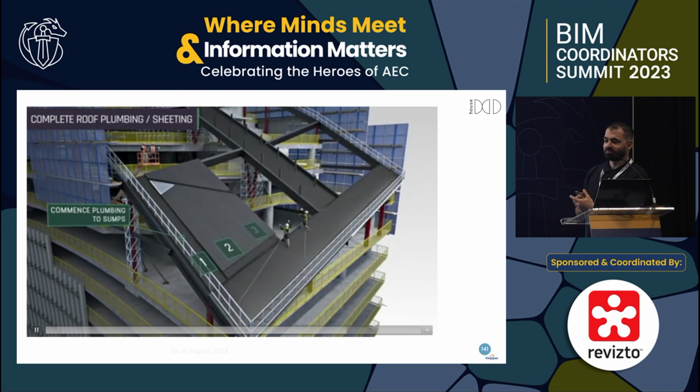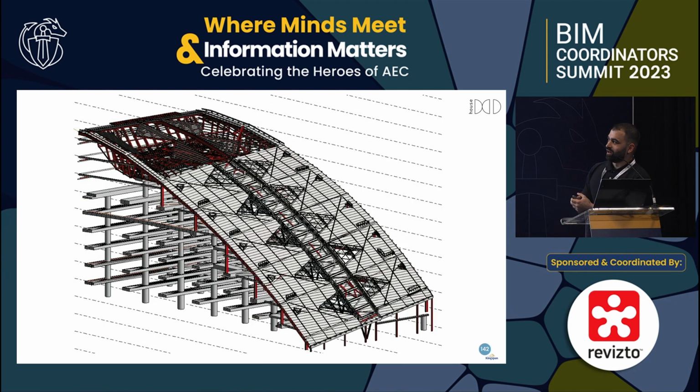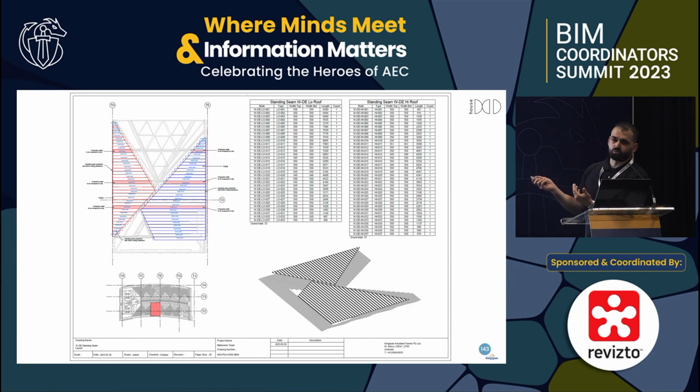Easy at the end. This is the building BIM model that we came up with at the end to mainstream that. Just to give you a perspective on how these were developed internally within the BIM environment, this is a shop drawing sheet that shows the components of the final layer of the sheet, which is the standing seam sheet itself. So the manufacturing facility needs these cut lists to produce it and then install it in line with the accessories behind it.